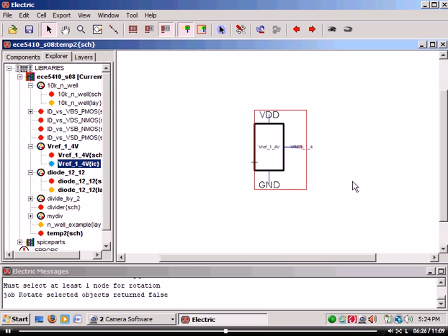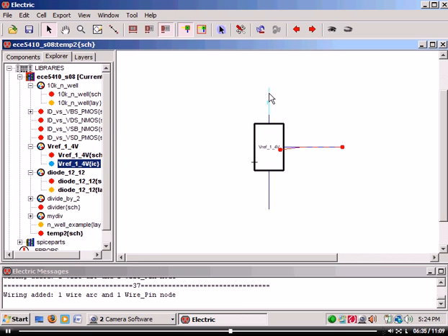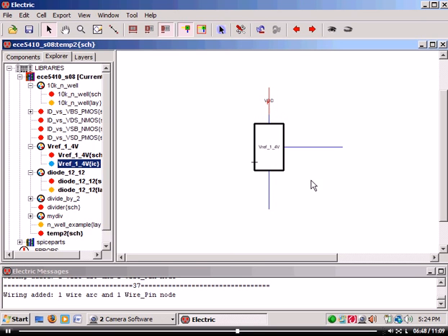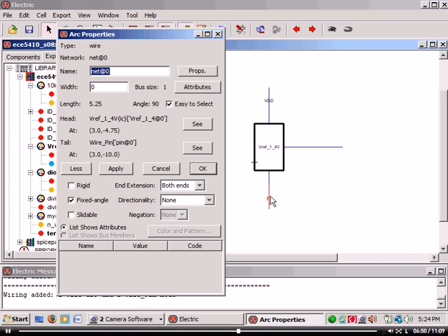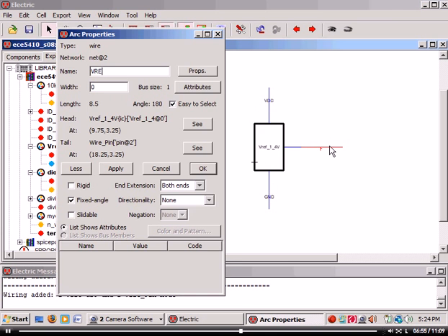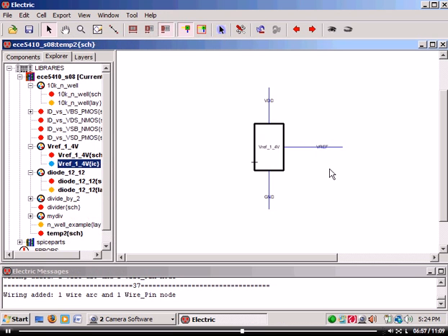Okay, so the key point here, I need to put the wires down. And then I need to label the wires. And see, if I was doing this icon, when you connect the wire up, the name goes away. So I put in what kind of text there? Annotation text, ground. So I'm going to call that VDD. GND. VREF. Then I'm going to come in and put my spice code.